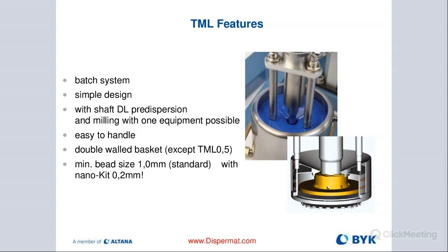Here, you don't really have to do much except sometimes replace the milling disc and the pumping wheel, and occasionally maybe the screen wears out. But that's the only thing you need to replace, and not often, depending obviously on how much you mill. For example, in my lab here, I mill quite a bit, and I have yet to replace the milling disc or the pumping wheel or the screen on my media mill that's 4 years old.